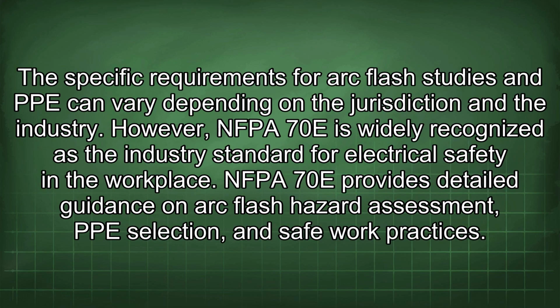The specific requirements for arc flash studies and PPE can vary depending on the jurisdiction and the industry. However, NFPA 70E is widely recognized as the industry standard for electrical safety in the workplace. NFPA 70E provides detailed guidance on arc flash hazard assessment, PPE selection, and safe work practices.